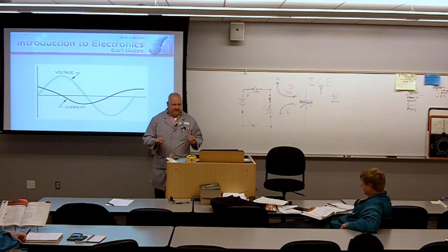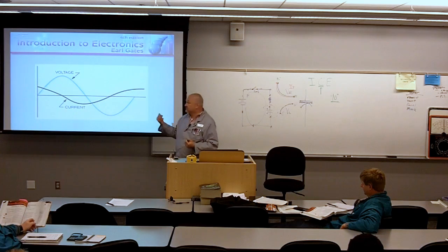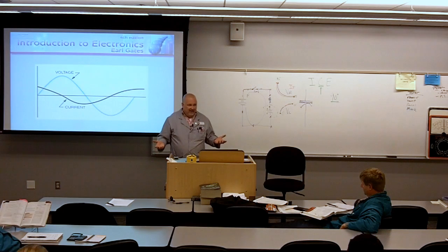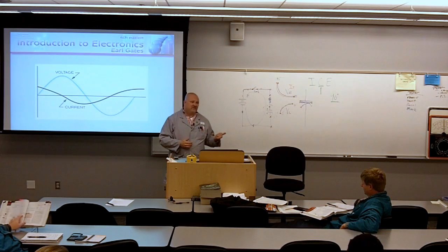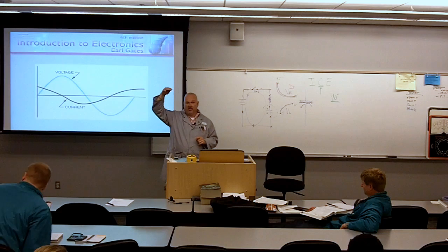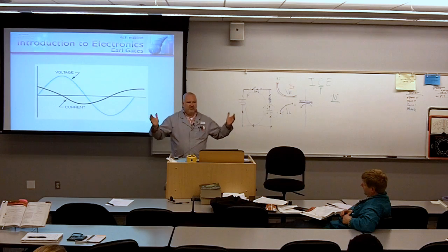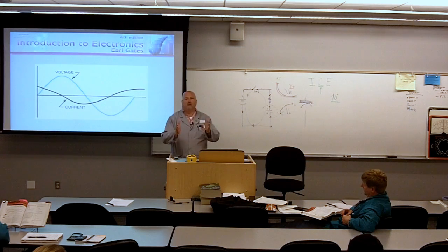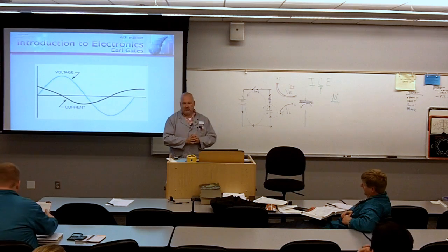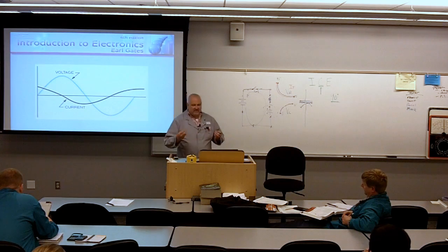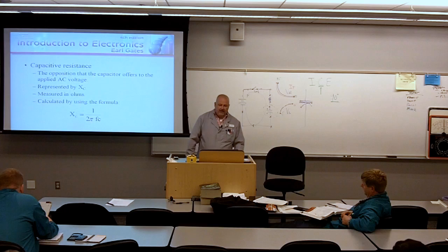It reacts differently. Because at a low frequency, this capacitor is going to be able to charge a lot quicker, right? At a low frequency, there's more time. At a high frequency, this capacitor is going to have a tough time getting up to that 100%, because as soon as it's on its way up, next thing you know, it's reversing itself. Because a higher frequency means more alternations per second. Plain and simple. So it's going to vary with frequency.